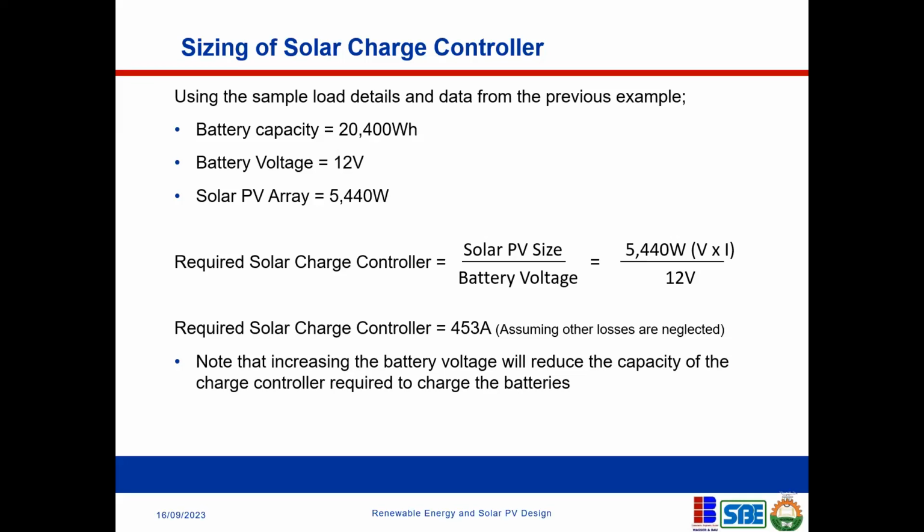Thank you very much for that question. It has to do with the capacity of the system you're designing. If you introduce 4 batteries, it will increase your cost, which means it's a smaller system that you're designing, so you can go for a lower voltage of 24, right? But if your system is big, then 48 or 24. Like you say, you have to look for a way to balance your design.